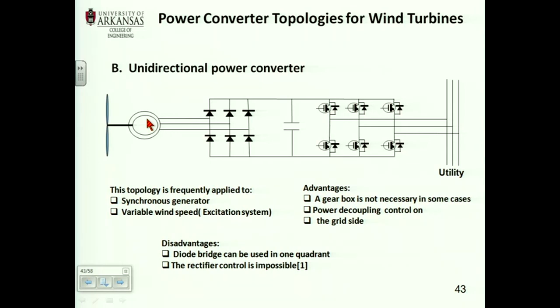If the power goes from the utility to the wind turbine, what do you have? A big fan, right? So now it wouldn't be an induction generator, it would be an induction motor, right? And so the wind turbine would be working as a fan, and I don't think that you need a fan in that application, right? It would be unique, but you wouldn't have many takers.